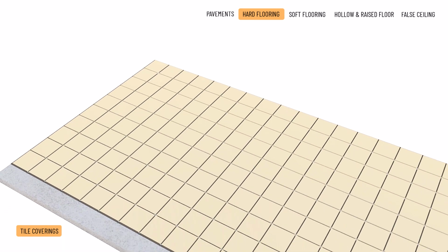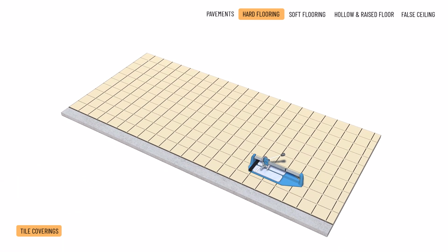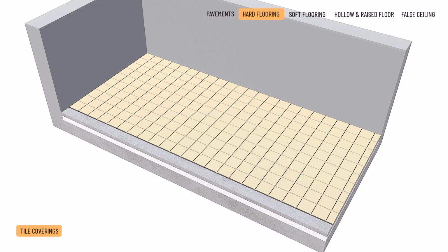At wall edges, floor transitions, or where custom patterns are created, tiles must be cut to size using a circular saw, angle grinder, or tile cutter. Along the walls, skirting tiles can be installed, glued to the wall above the edge of the floor tiles. The finished covering and grout joints must be cleaned of adhesive residues.